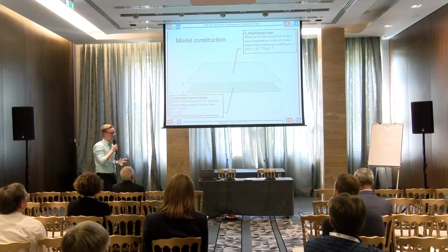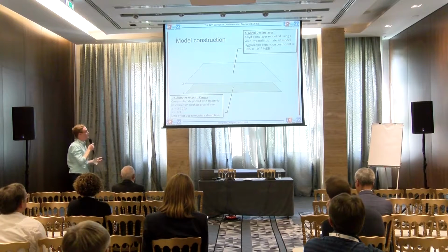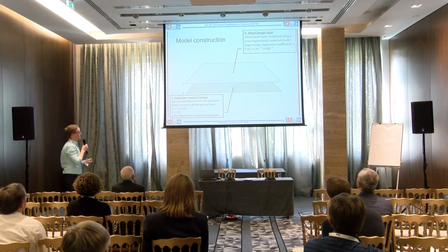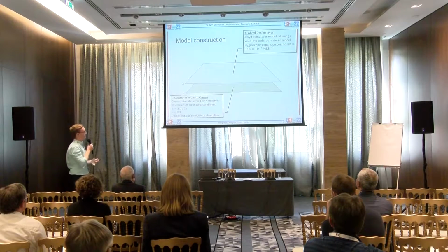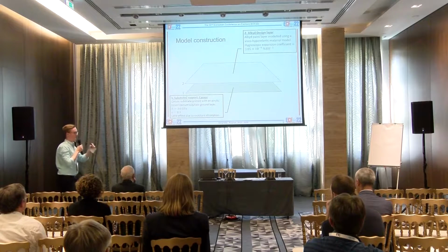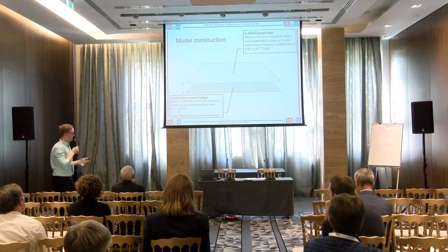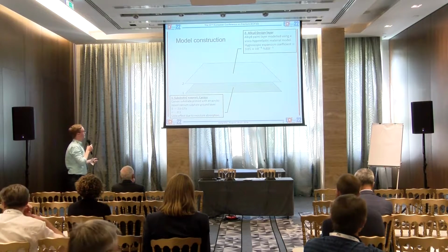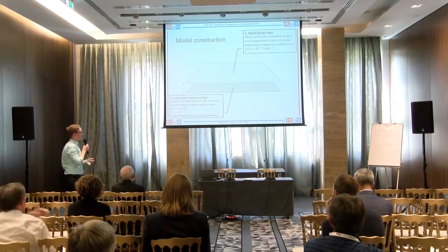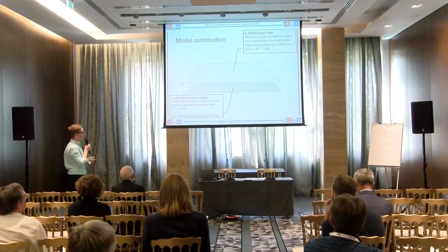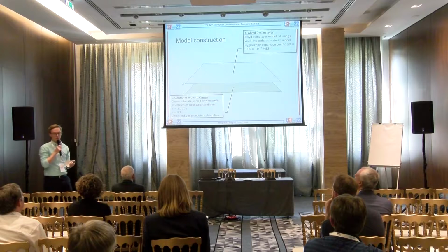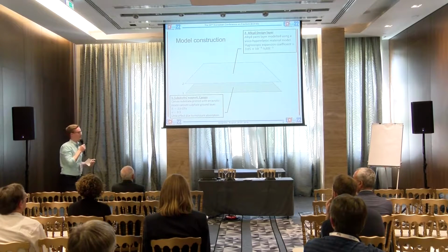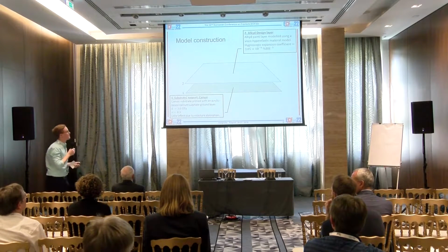So our model construction, we're just considering 2 layers. First, we have the substrate or support, and we're looking at a canvas. The canvas has been primed with an acrylic-based calcium sulfate ground layer, and we're just considering this as 1 layer. From literature, we've identified that this can be considered as linear elastic with a Young's modulus of 3.6 gigapascals, Poisson's ratio of 0.3, and it shows little effects to changes in relative humidity.